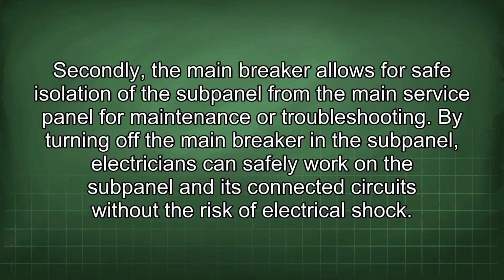Secondly, the main breaker allows for safe isolation of the subpanel from the main service panel for maintenance or troubleshooting. By turning off the main breaker in the subpanel, electricians can safely work on the subpanel and its connected circuits without the risk of electrical shock.